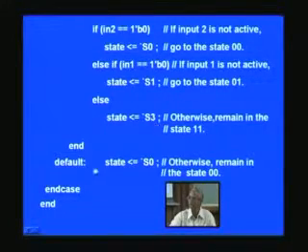And then why default? It is not just customary. Probably it may so happen that a tri-state Z or don't care situation arises. It may not arise in a sequential circuit, but it's always safer to put it here. And another point is you may have 3 bits instead of 2 bits, in which case you have used only S0 through S3. So S4 through S7 are not utilized. So what will happen to such cases? You should take that into account as such. Only then it will be trouble free.